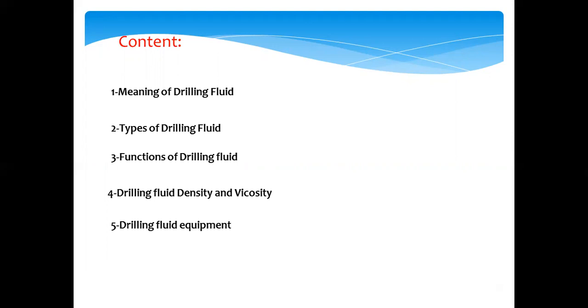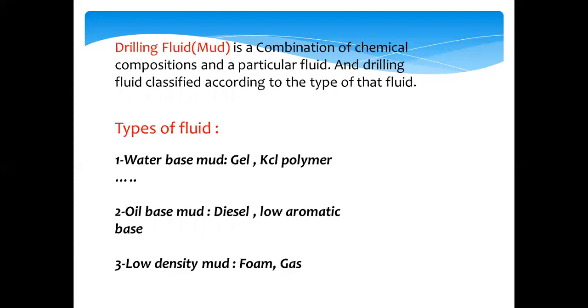In this lecture, we're going to learn the meaning of drilling fluid, different types of drilling fluid, the functions of drilling fluid, other properties of drilling fluid, and finally the drilling fluid equipment in the field. Okay, so now let's get started with the meaning of drilling fluid.